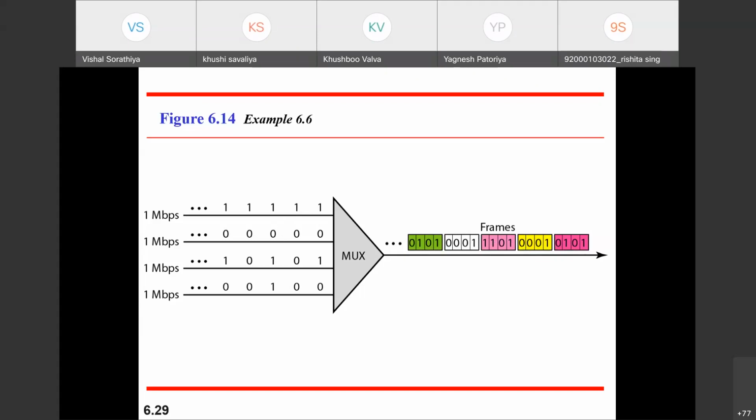It has one timer circuit inside, and the timer circuit is set up with one specific time duration. Let's take 1 microsecond or 1 millisecond. In that duration, only one station is allowed to speak. Then it will change its counter to another station, then another station. Likewise, this loop is going to rotate, and the frame is generated depending on whichever station is speaking in its time duration. So likewise, time division multiplexing happens. We are multiplexing time; we are multiplexing the data from different times, generated by the different stations.